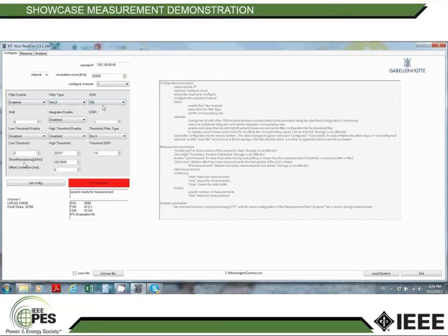Down here, you can see the shunt resistance in microohms. It is set to 522.8. Usually, we would use a lower shunt resistance in order to limit heat dissipation. We usually use between 10 and 100 microohms max. But here, as explained before, we want to measure a small grid current, so that's why the shunt resistance has been chosen this way.